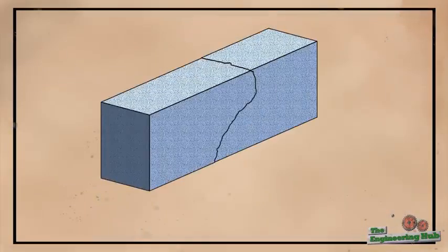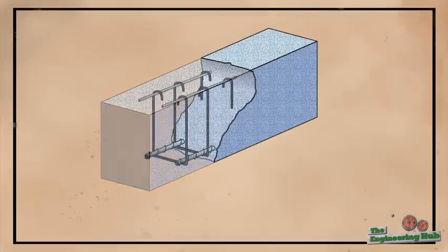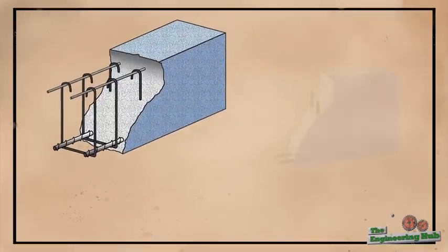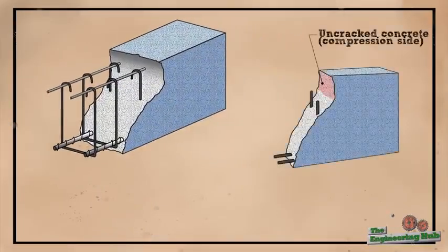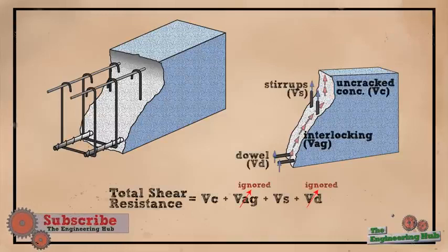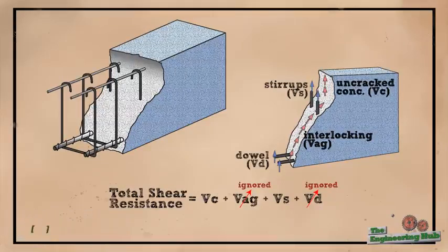In fact, the only concrete shear resistance for regular cast-in-place beams comes from the uncracked concrete on the compression side. The intrinsic concrete shear stress is often insufficient for a safe design. Based on the applied shear forces and the width of the inclined crack, engineers can calculate the amount of reinforcement needed. For higher shear loads near the supports, the stirrups are placed closely, which ensures that several of them will be engaged within an inclined crack.